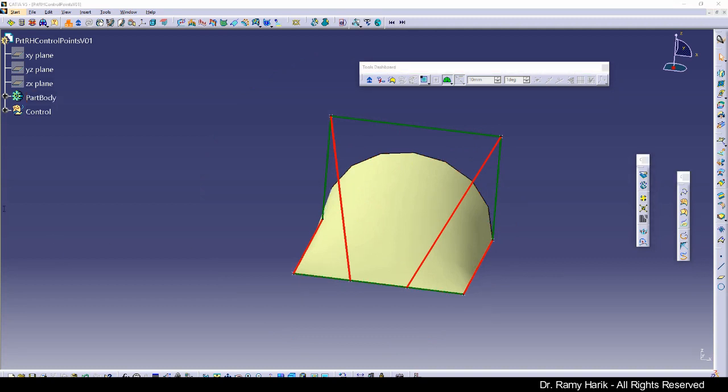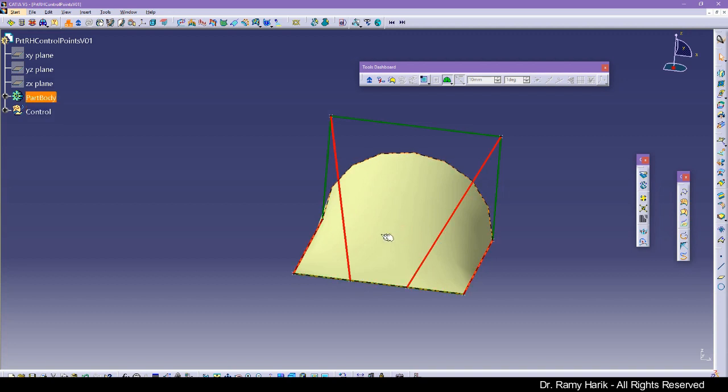Now, a lot of the time you want to create curves on these surfaces. One of the most important curves that we have is what we call isoparametric. This is when you fix one of the parameters. Let's say I want to get the curve for u half, which means the middle of u. If this represents u and this represents u, this point in here and this point in here is for half u. So if we want to create the curve for half u, I can come on the parameter in here and select the surface that I have.